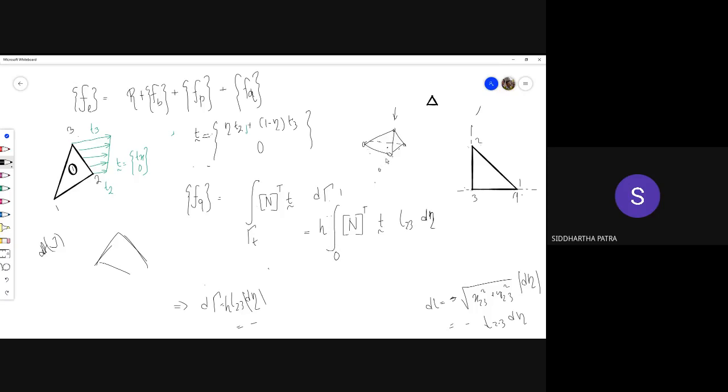Then the solver takes a smaller time step and does the solution. The other thing could be that you are using a different numbering, that is a clockwise numbering. Then you get an indication of a problem which is actually not there. The element might not be flipping through calculation, but the solver thinks there is an error.